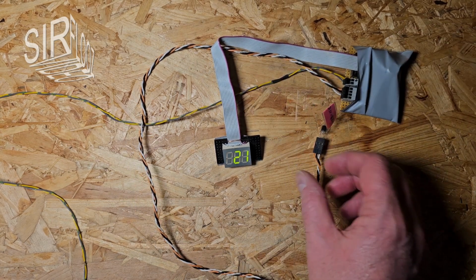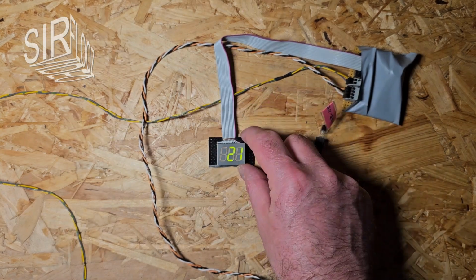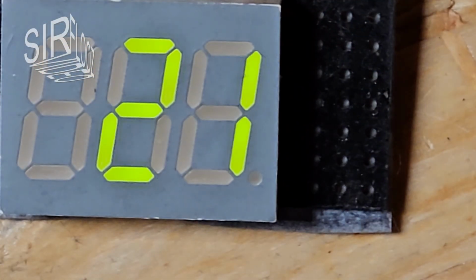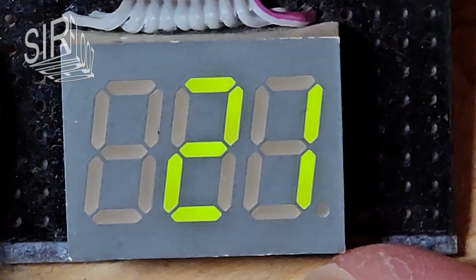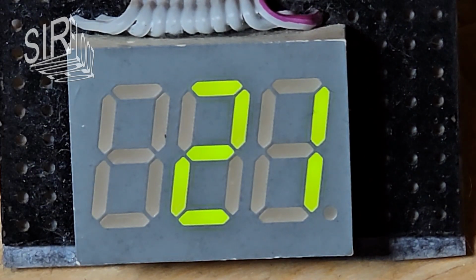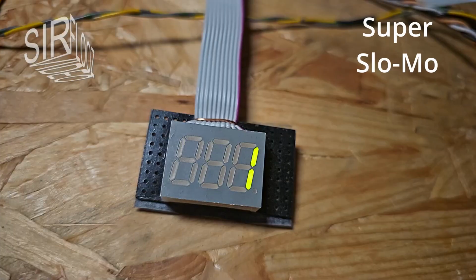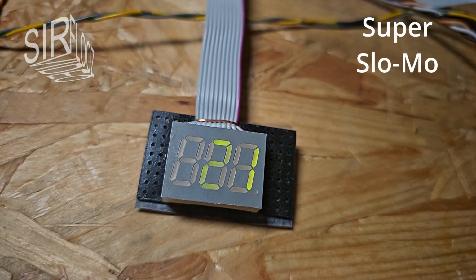See here a temperature display with a digital DS18B20 sensor that I built some time ago. Every time the MCU fetches the new temperature data from the sensor via a one-wire interface, that's every 10 seconds, the LED display is interrupted for a few hundred milliseconds. It's hard to see on video. With the shift register, the LED display would not be interrupted by this.